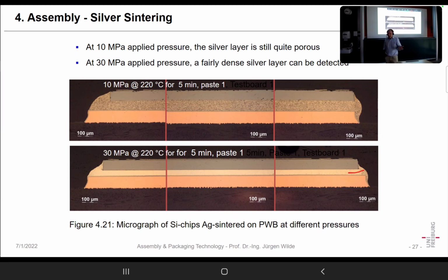Yeah, very good, 850. But you would not like to do that on an IGBT chip or any other silicon chip. It would never survive it. So you must go down. But how can you decrease the sintering temperature? And there are two tricks. One of the tricks is making finer silver powder, going to 1 micrometer or lower. Then the sintering goes much faster, even at low temperatures.